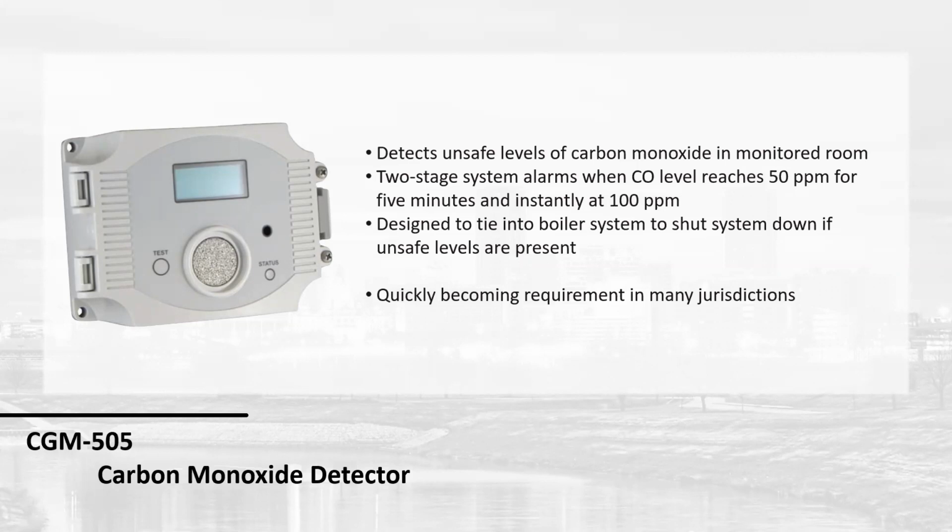Yeah, like I said, one by one. Georgia just passed that all mechanical rooms require a CO monitor, so it's coming. It would not surprise me if it's a federal code in the coming years. So put it on all your boilers. Mine or someone else's, it doesn't matter.